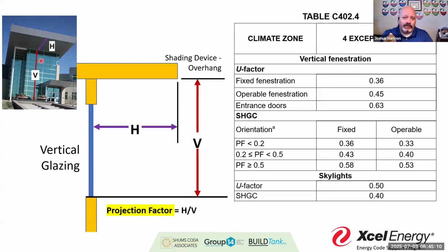The contractor went out there. As I looked at the stickers on the windows, they were wrong, right? They had gotten halfway up and they said, well, we don't want to take them off, we'll just leave them, right? And it's like, well, these windows aren't going to perform the way they're supposed to. Now they're going to get more heat into the building than they were supposed to.